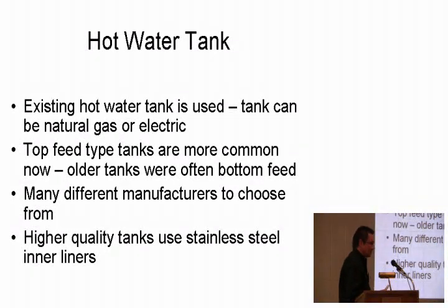That's sort of an exception to the case. Top feed tanks versus bottom feed, just a different type of tank. Some of the higher quality tanks will use a stainless steel liner inside instead of a glass coated or ceramic coated steel. And some of the stainless steel tanks inside have lifetime warranties on them.